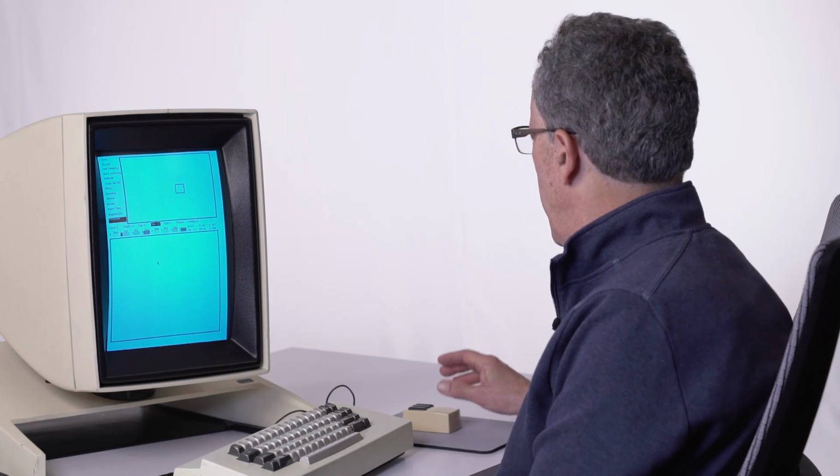I'm going to begin by drawing first on the metal layer. So you select the layer that you want to draw on, and then you point and click at the two endpoints of the line you want to draw. You then go down here and draw another line. The metal line is used, for example, to conduct power and ground to all of the circuit, and so is often a common starting point or reference point for the design of the rest of the chip.